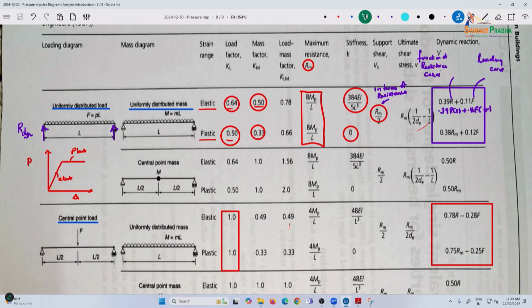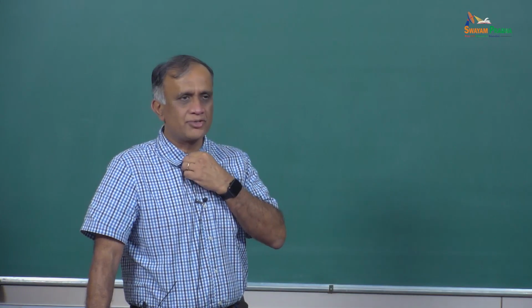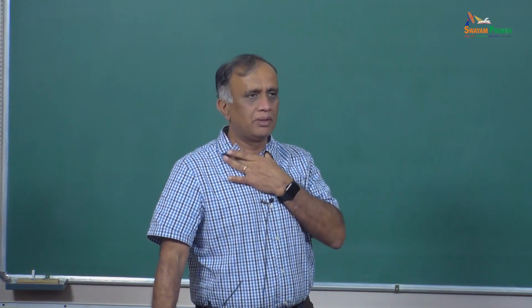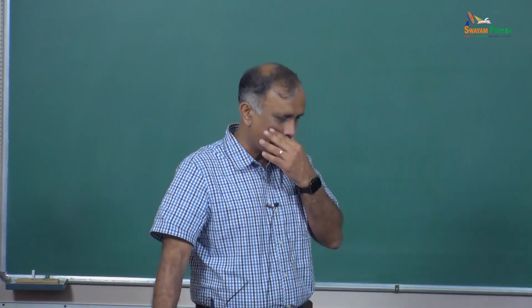So, one thing you could think of is, should you do both an elastic analysis and a plastic analysis? You can take the average stiffness equal to KL elastic plus KL plastic. As an engineer, you have a lot of leeway to work with different assumptions, and a reasonable assumption to do just one analysis is to take the average of the two stiffnesses. Is it accurate? No. But does it work for design purposes? Perhaps.